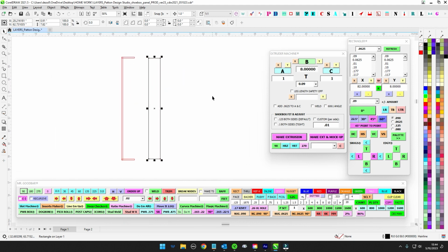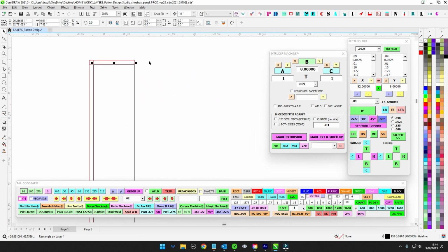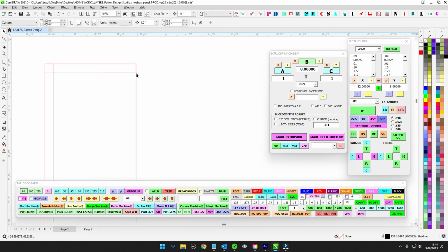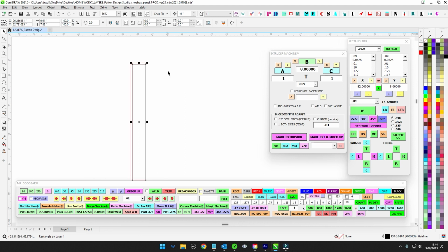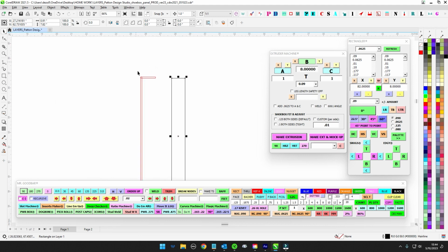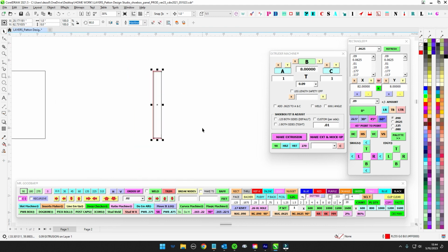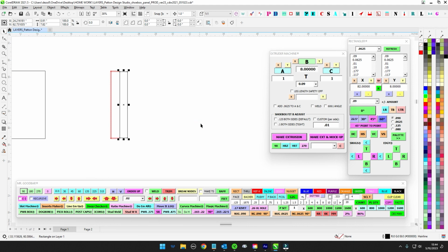So when it comes to making a shoebox, just like the name implies, when you buy a pair of shoes, the lid fits over the main box. So in signs, you have a panel, which is the lid, the red, that is going to slide over the backer piece. And the backer piece can either be mounted to a wall, or it could be mounted to another sign as a panel, you know, for a tenant sign or something like that.